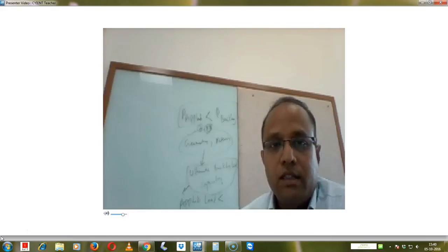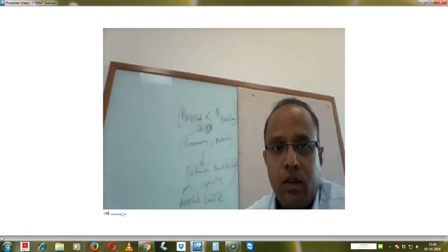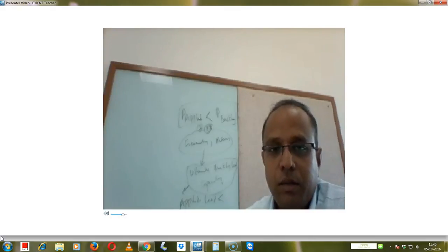So whenever a structure is subjected to compressive forces, it can undergo buckling, a bifurcation of equilibrium from deformation. So there will be a disturbance to the equilibrium, and also failure due to instability of the equilibrium due to large deformations. So there are two ways. One is related to equilibrium of loads, whenever buckling happens. Otherwise, due to large deformation, the material will go into inelasticity.